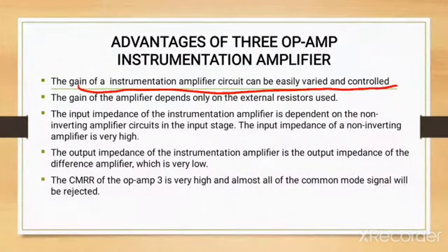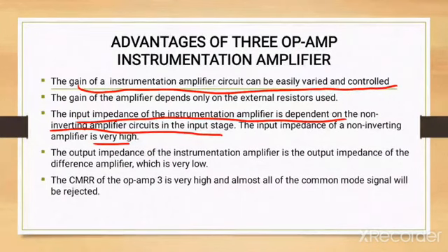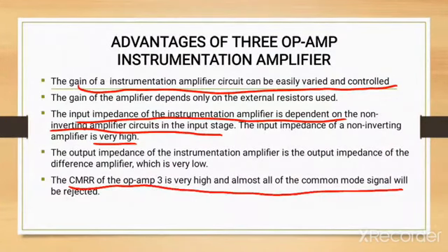The input impedance is also very high. And most important, all the common mode signals will mostly be rejected, because the CMRR of the third op-amp is very high.